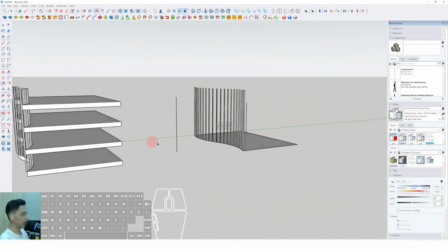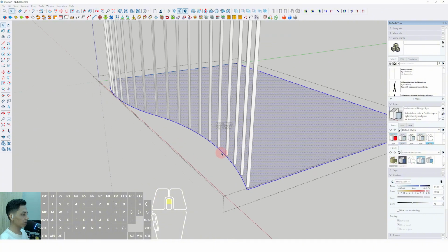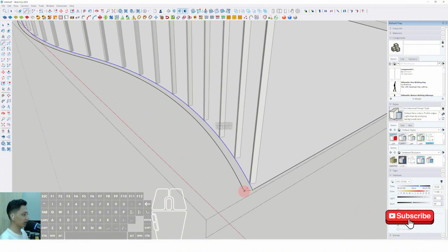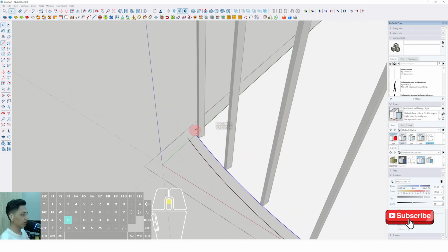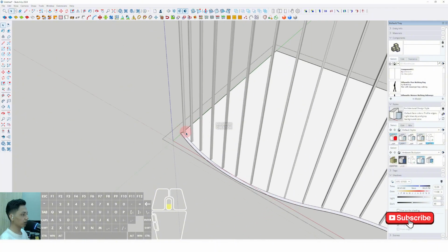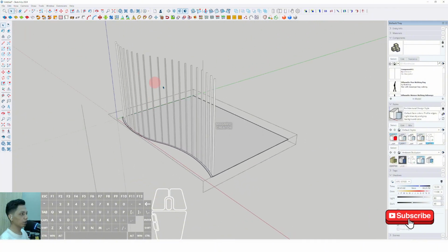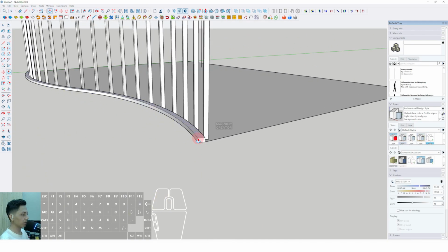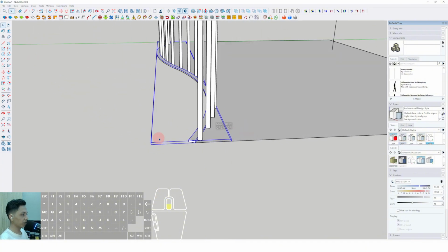And then now you can make another horizontal frame. You can select this smooth curve and offset it outside around 300 and enter, and we can close this another line. Then we can click the surface and select edit, copy, exit from the group and edit, paste in place. Then we have to push it up around 100, enter, double click, make group, and we can